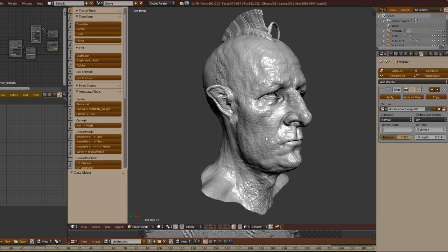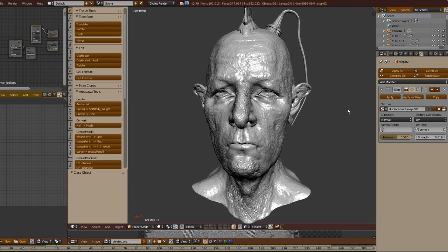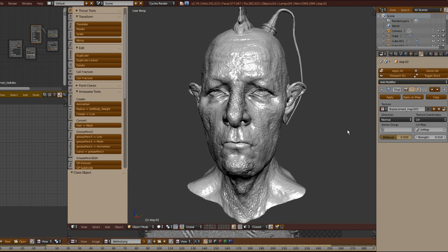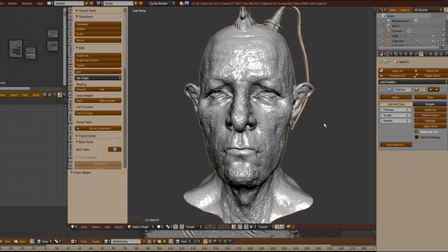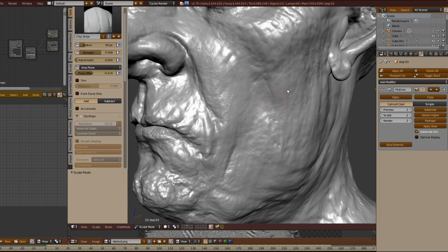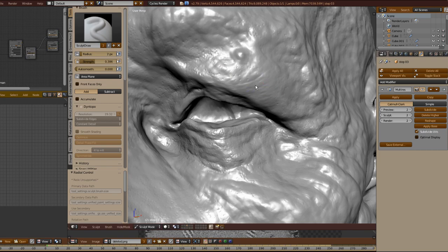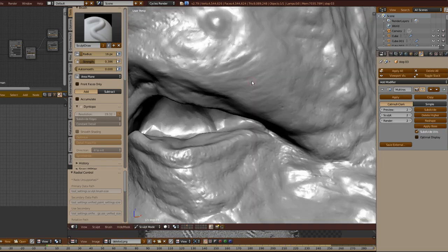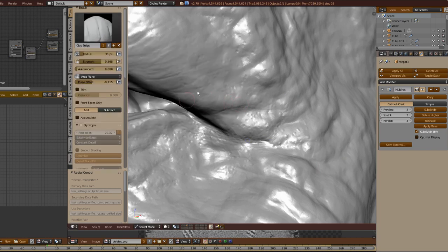In this same mesh, I decided not to do the pre-topology process, and I went through my work to see how far that system could take me or support my work. So, I added the multi-resolution modifier. To my surprise, even with a poor topology, the multi-resolution system behaved perfectly on the first level of subdivision, and I was able to sculpt perfectly and seamlessly through the mesh.